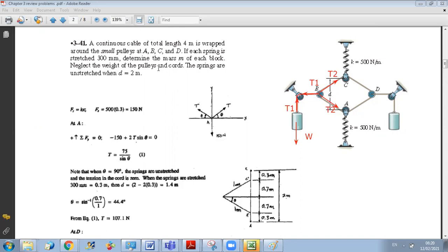And in order to do this, I need an angle. I need to project my forces. So I need to know what this angle here is. Okay? And to know the angle here, I need what? I need the distance D. So this is why I need to find this distance. Because now, if I know that this distance is 1.4, then this part here is 0.7, okay? And I know that this length is 1, so I can find this angle. I can write this angle here, let's call it alpha, for example.